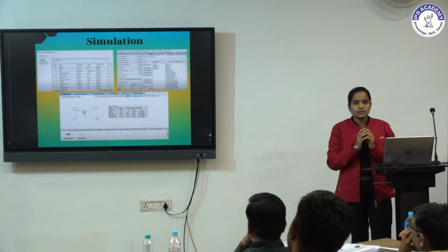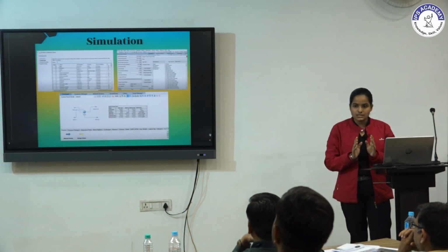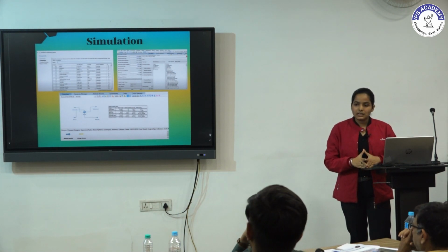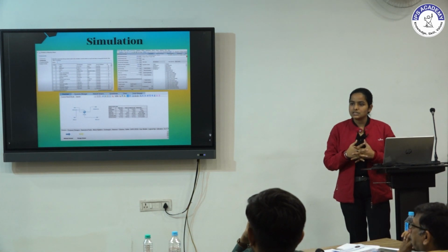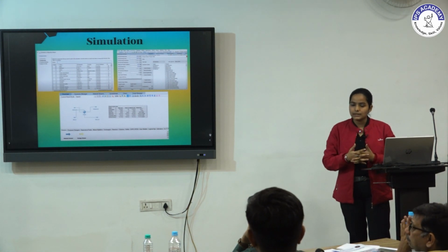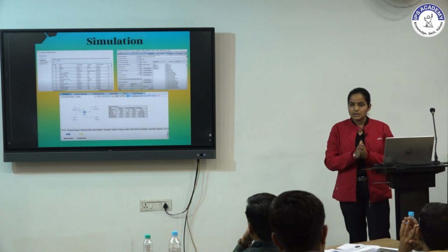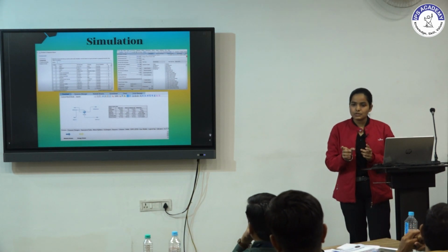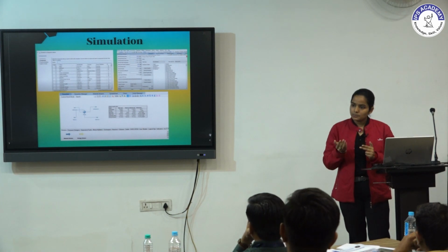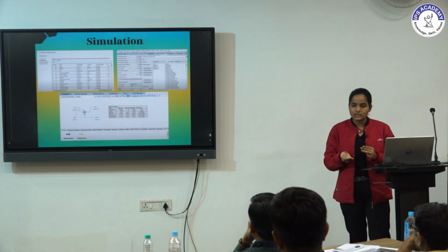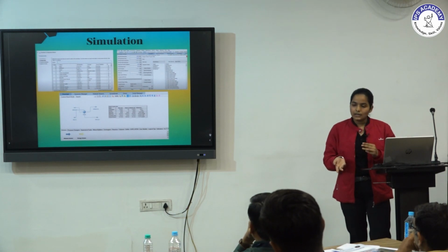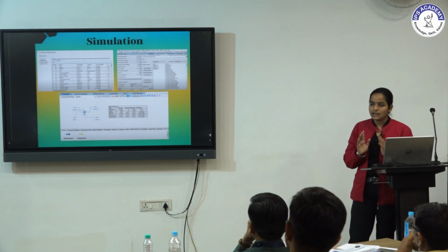So firstly, we should open the process simulator, and in the process simulator a wizard window will appear, in which we have to choose the compounds, which I have used as methanol and water. Then we should introduce a material stream which should be named as methanol in, and all the desired values should be mentioned in that. And another material stream should be introduced, and it should be named as water in, and all the desired values should be mentioned in that too.